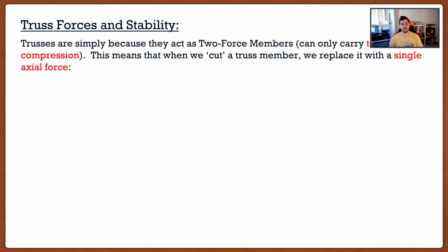Now, when it comes to trusses, some other groundwork we have to talk about is the idea of truss stability, as well as the forces inside of a truss. All right, so it's actually not going to be too bad. We've discussed before that trusses carry either tension or compression. Now, what exactly does this mean? Well, it means that when we cut a truss member, we have to replace it with a single axial force.